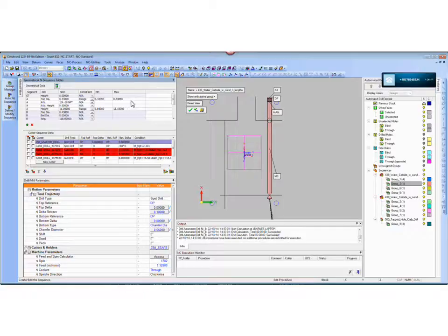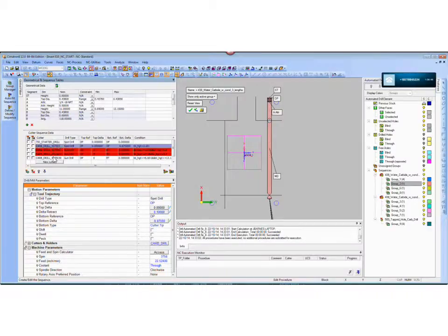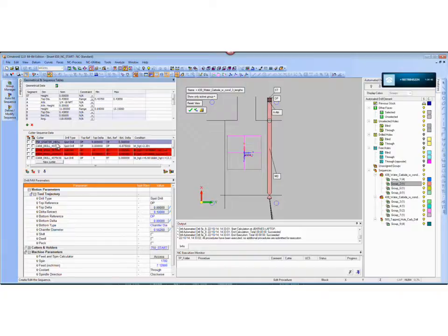Here's the depth from 850 to 13.15. Now 13.15 just happens to be the full depth that I can drill with my 30 length ratio drill. Anything more than that, and the 30 length isn't going to do it. So I went ahead and minimized that range. Now down here, these colors mean something. Actually, purple here is just a highlight, so don't worry about that color. But the red means that this one's not being used.